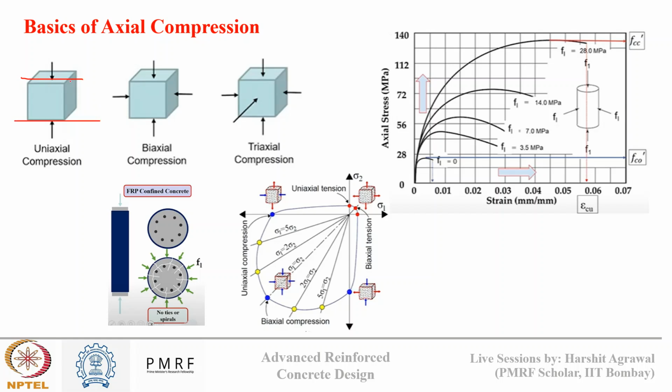There is a frictional effect between the CTM plates and the concrete which resists the bulging effect that is created by the loading. This is known as the end plating effect. But near the middle this frictional resistance becomes weak, and there are outward stresses that are generated due to this loading, which results in a cup and cone kind of failure in concrete.